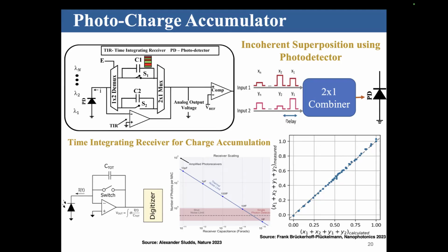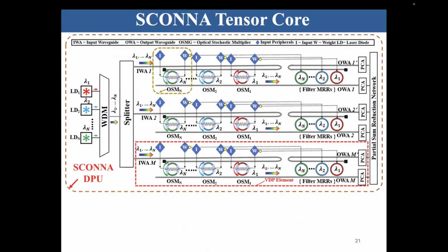We also have to convert the stochastic bit stream. We have done the multiplication using the optical AND gate. Now what we do is we count all those ones, and then we accumulate those. So we convert the counting of ones into an analog quantity, and counting of ones basically converts the stochastic number to an analog number. And so forth.